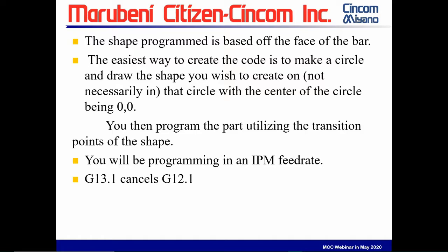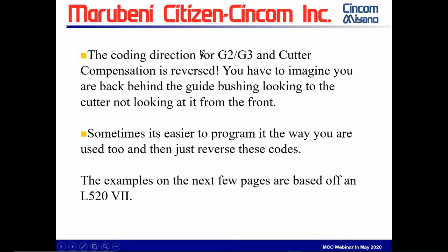You would be programming in inches per minute feed rates, and G13.1 cancels G12.1. Now that might have been a little bit confusing, but it'll show up in the next few slides, and we'll clear that issue up.